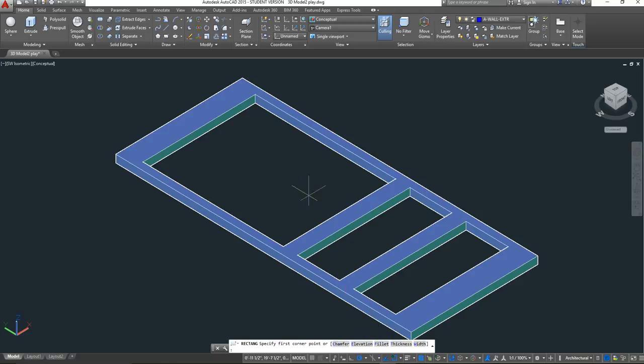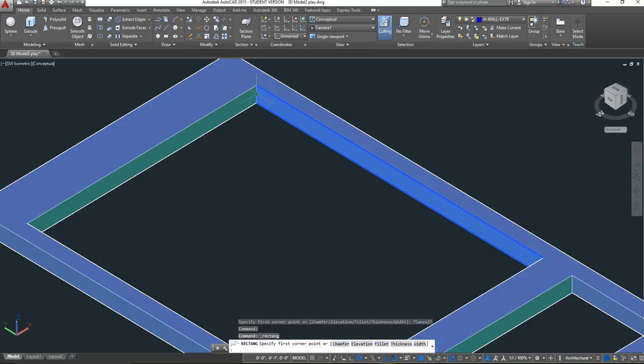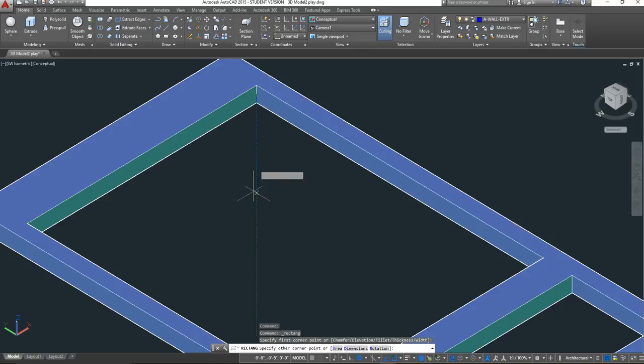Okay. Alright, once I have that, again, home tab, I want to get my rectangle tool, and I'm just going to go from the midpoint of the inner part of that door, that first panel. I'm going to click once to start that rectangle. Actually, let me escape out. Let me make sure that I'm in my top. So home, go over to coordinates, click down on where it says unnamed, and I just want to make sure that I'm drawing in my top layer.